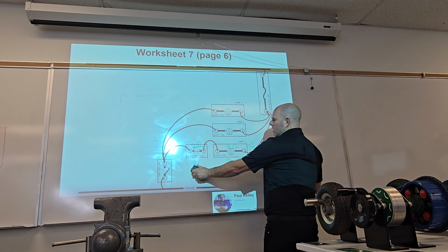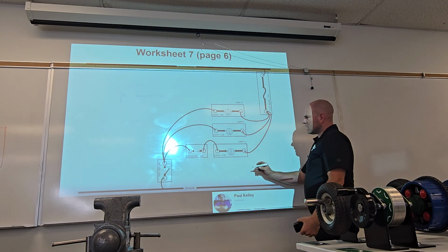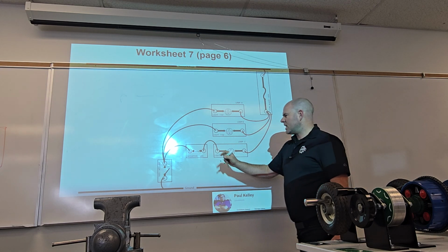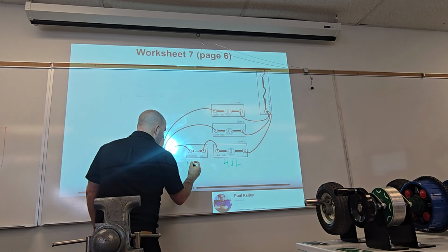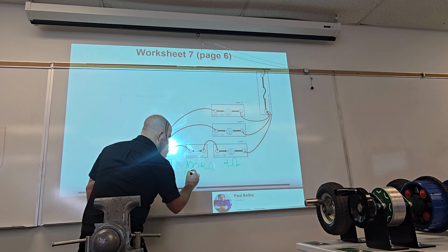Now in reality, let's say it wasn't a resistor. Let's say it was corrosion in the connector. Let's say this was a 4 ohm bulb, which would be pretty low, by the way. And let's just say this was, like I said before, 100 kiloohms. You know what that means, right? That's 100,000.